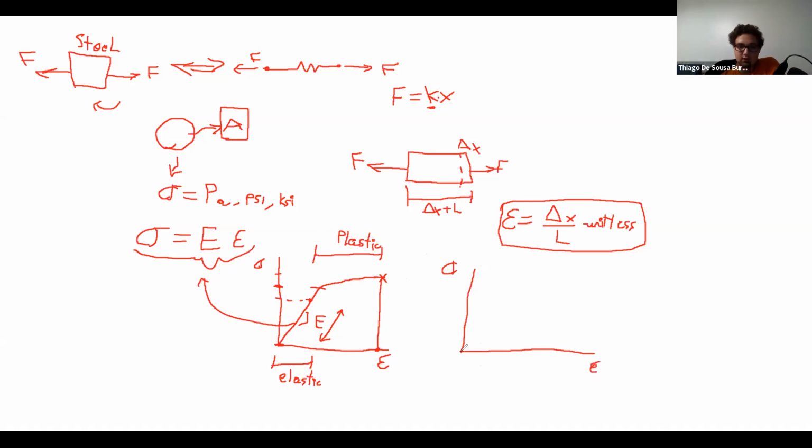So much like a metal, we're going to have a linear section to it, and then suddenly our composite's going to fail. There's basically no plastic region for a composite. Once it starts creating these things called voids inside the material, once it starts actually separating the physical atom connections, once it starts actually separating that chemically, in a composite, it will fail.